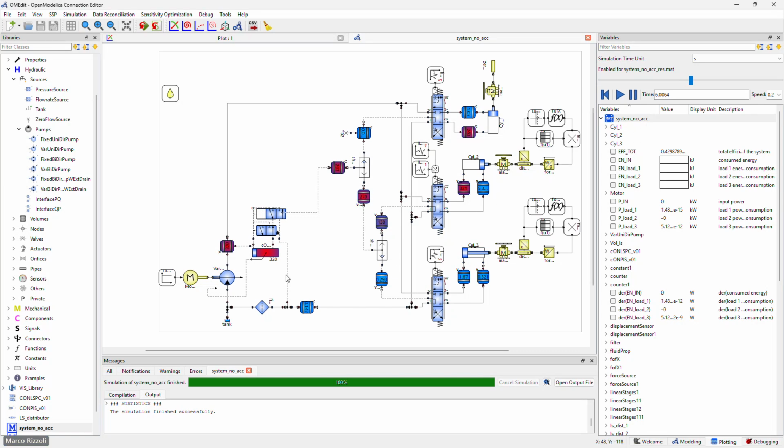After, we move the third one, which is also requiring almost more than 200 bar at the pump, and at the end the pressure compensator is stopping the displacement, the flow rate of the pump, since we reach the end stop and reach the max pressure in the system. To end the cycle, we will retract the second cylinder right now. This is the retraction phase, and we will stop this type of cycle.